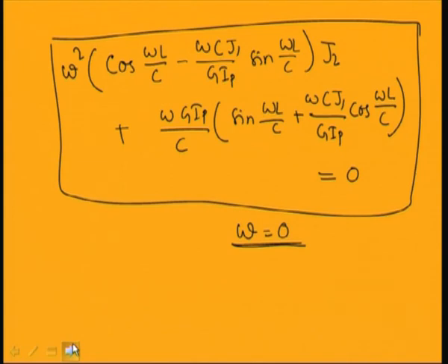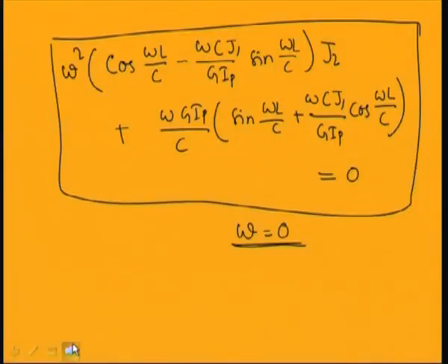In this case I have studied 3 different systems. In one case both ends are fixed, in another case one end is fixed and the other end contains a mass or inertia, and in the third case both ends contain inertia terms. In these 3 cases, only in the first case, that is fixed-fixed, you have a closed form solution, or you can determine the solution manually.